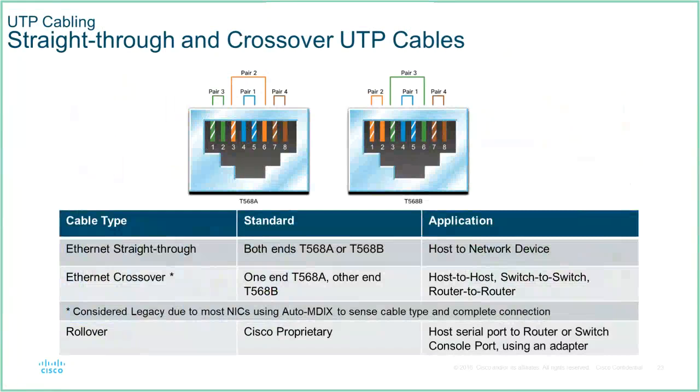Now, the way it works is we need an A and B plug if we want to create what's called a crossover cable. Crossover cables were generated from the old days, where we would have a transmit and a receive pin on our source and destination, our A and B. So when we transmit, we don't want the transmit going to the transmit pin.